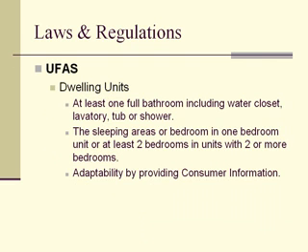and tubs or showers also at accessible heights and with the requisite dimensions. Also, for the sleeping areas in these units, the requirement is that if it's a one-bedroom unit, that one bedroom must be accessible. If it has at least 2 bedrooms or more, then at least 2 bedrooms must be accessible. And by saying that it will be accessible, basically you have to have the requisite door width, the closets inside of them have to be accessible, hardware, and different elements also that we will see.